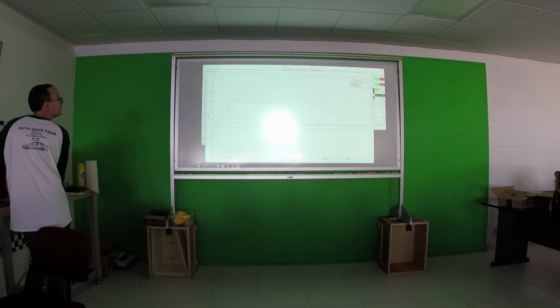We correlate the change in throttle to the change in RPM. Torque. And all these too, you can see it automatically named these graphs based on what the DBC file said, but if I double click on it, you can name it anything you want. And also right clicking, you can save this graph image to file. It'll save the current view to a PDF. So you can use that.